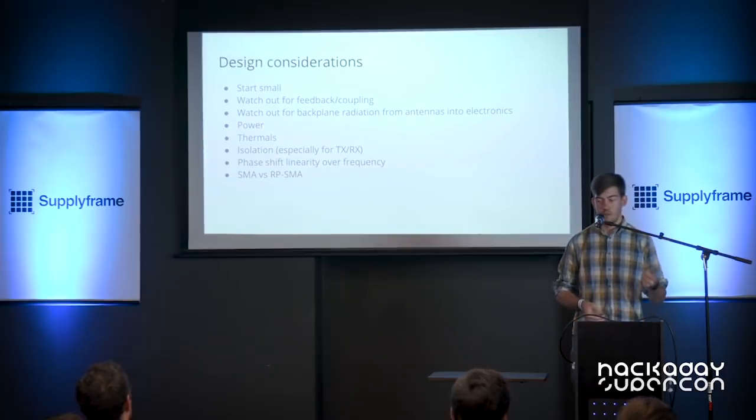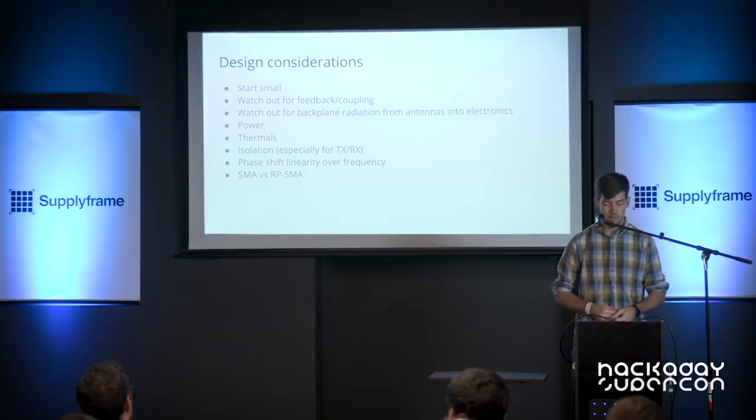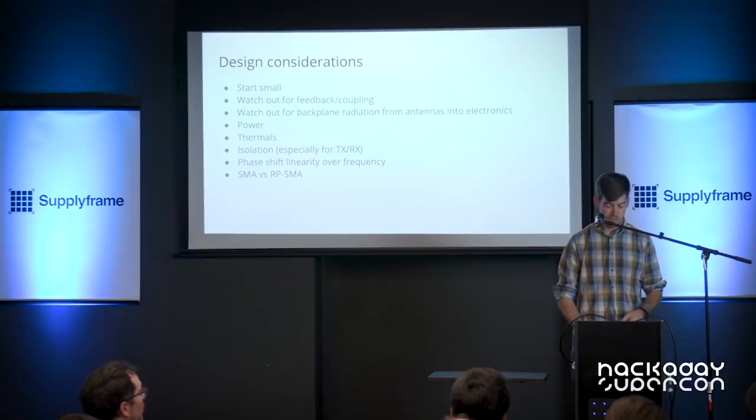And they'll screw together perfectly, and it will seem like nothing is wrong, but everything is wrong. And so you need to buy adapters for it, and there's 2 different adapters. There's one that goes male to male and one that goes female to female. And it's good to just buy a bunch of them because they're cheap. And at some point, when it's 3 a.m. and you screw in an antenna and it's not working, you will realize that you need one of these.